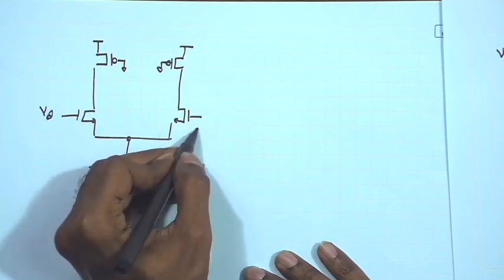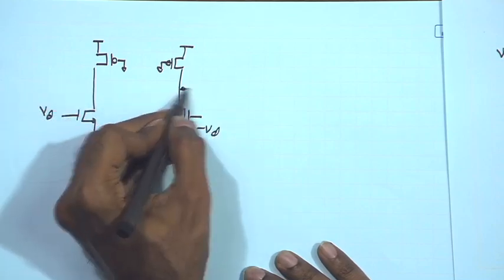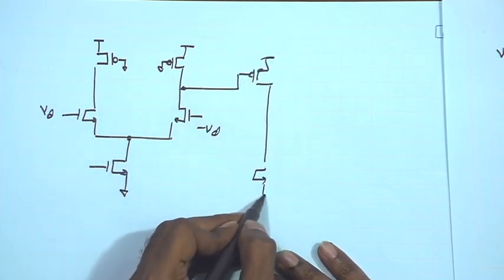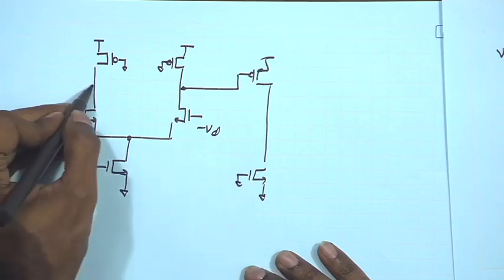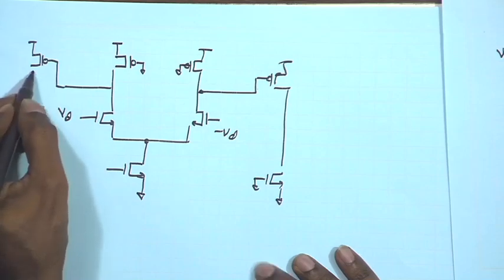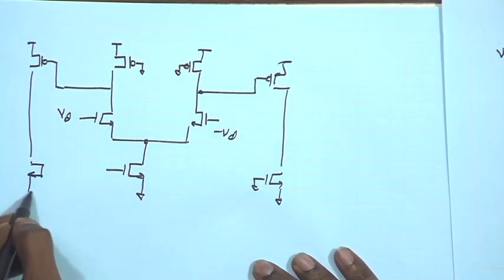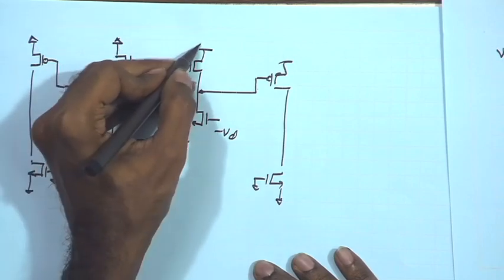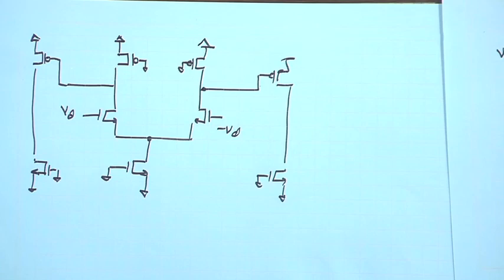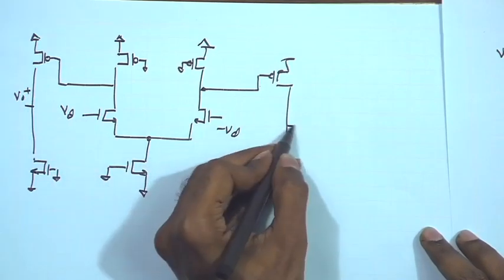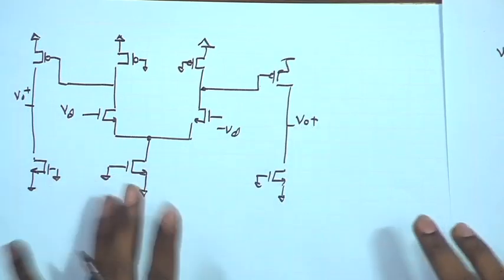So, you have Vd and minus Vd, and then you have the second common source stage. So, all the DC bias points I am putting to AC ground, and here once again we know that the differential gain from the input to the final output is having a (gm ro/2) square term.